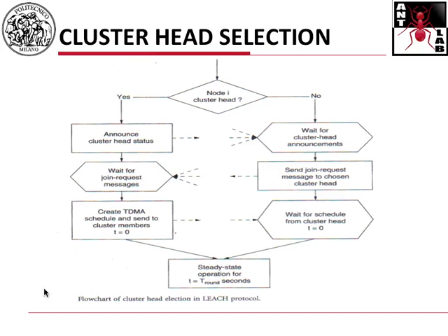Okay? For example, if the medium access control within one cluster is 15.4, all the non-cluster head nodes will have to wait for the beacon, which tells them what the frame structure is, what the beacon interval structure is, what the GTS is, what the CAP is, and so on. Okay? So as you can see, clustering can be used in composition with what we have seen so far. It can be used in composition with 15.4 as an underlying medium access control protocol. Okay? Questions?